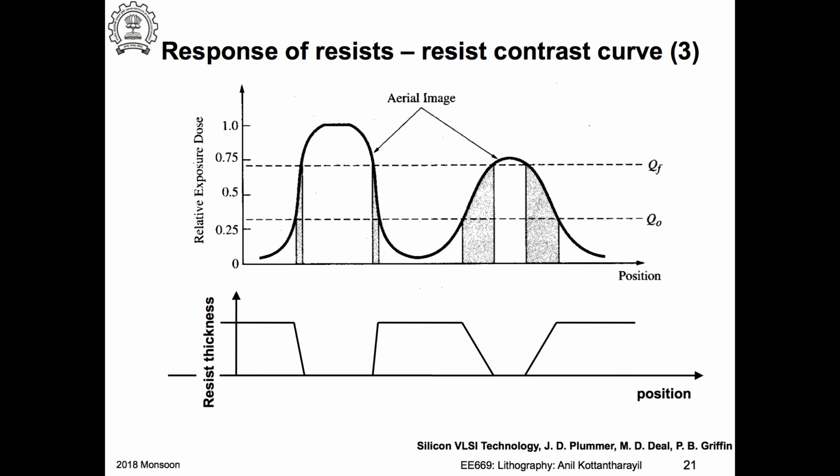But they would always come with, sometimes they give you the resist contrast curves, and the recommended process you should do. This is just one of the examples. Always look at the details of the photoresist data sheet to see what exactly is recommended by the manufacturer, start with that process, and then you can play around that baseline numbers.